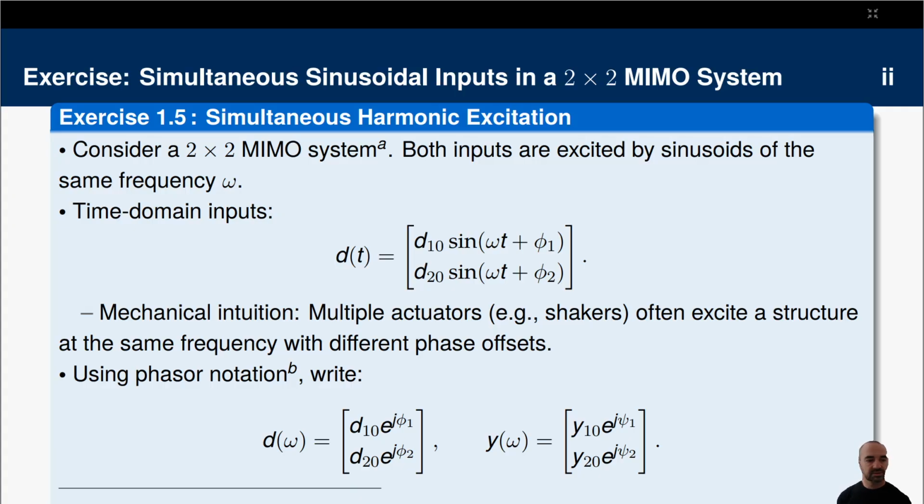Then we have the phasor notation, as we talked about, and at this point, once we use the phasor notation, we stop chasing sinusoids in time and instead manipulate complex numbers. You may think that G, again, just to remind you, e to the j phi 1 and phi 2 and psi 1 and psi 2 are approximations, but they are not, because we're looking at the system at a certain omega, so it's an exact representation for a steady state LTI sinusoidal response.